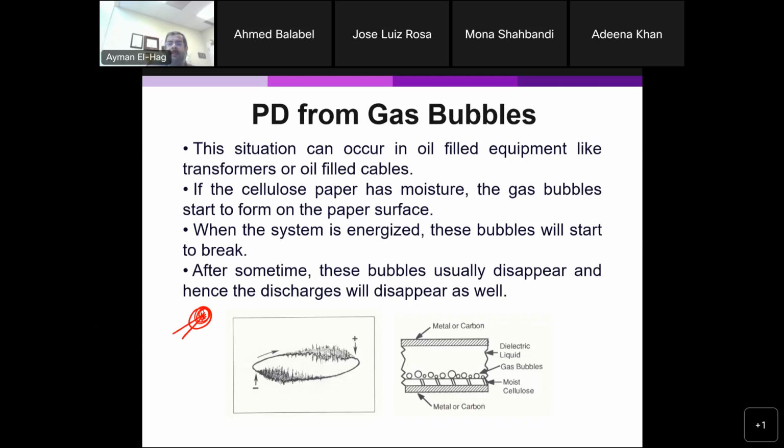So they were measuring the partial discharge, and they thought it was something like an air void or air bubble, because the transformer size was large. Then they ignored it, and at the end of the story, that manufacturing premises, I think because of that incident, had to shut down.